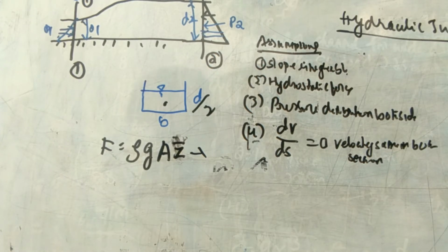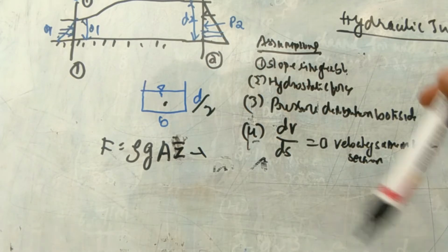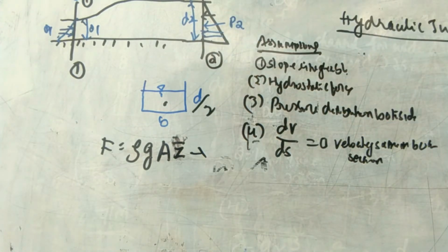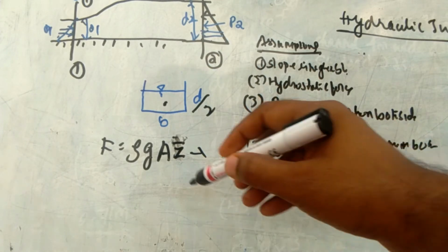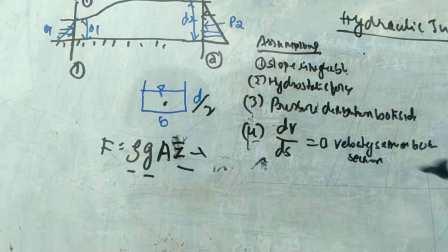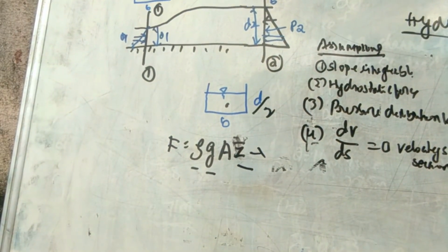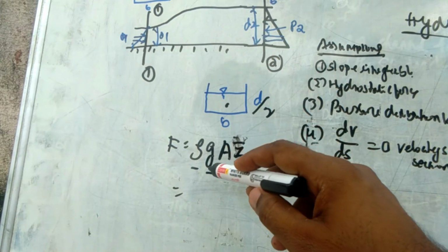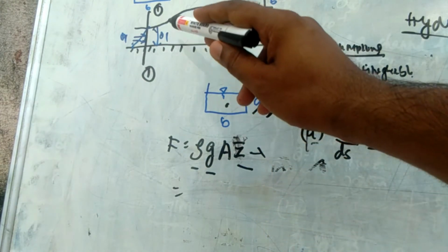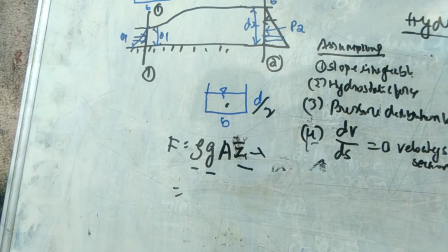And center of gravity is also important for this, because when the gravity is not proper, it comes out from that material, then the body will incline and a slip occurs. So for that reason gravity is also important here. So the density, g, A and z bar, those 4 parameters we are using in that derivation. F is equal to rho g A z bar, where rho is the density, g is 9.81, A and z bar. For one section, z1 bar and z2 bar. Those two forces, what are the forces acting, that we can consider.